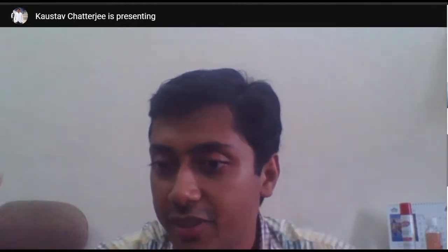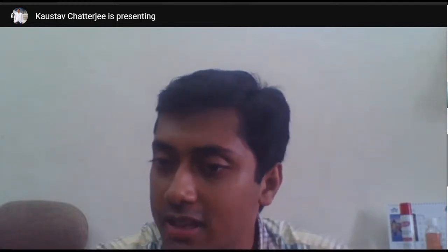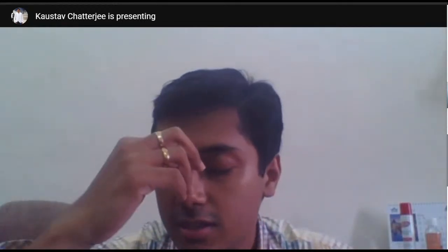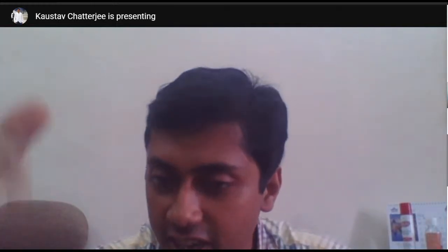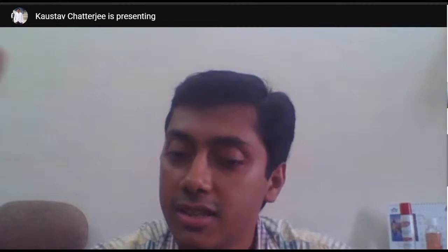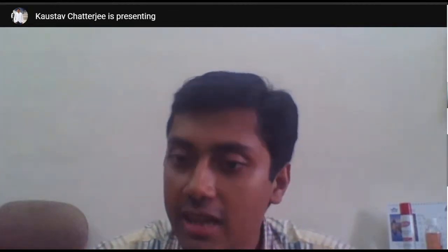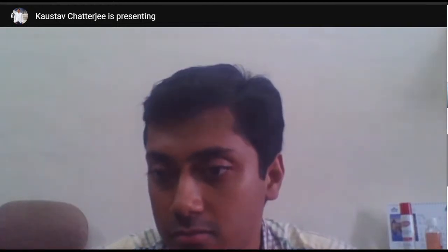The few things I have done mostly are the Mohr-Coulomb model, the Byrne model, and the Cam clay that I am working on. If you use the corresponding constitutive equations for the particular model, and integrate them over the time domain in FEM, by taking the Lagrangian interpolation function, then I feel, in my opinion, that it can be solved.